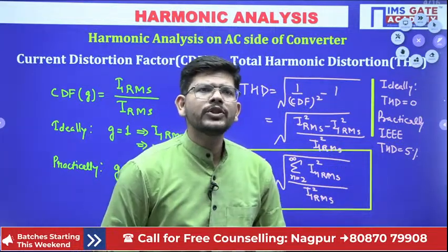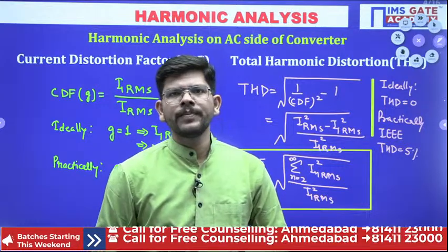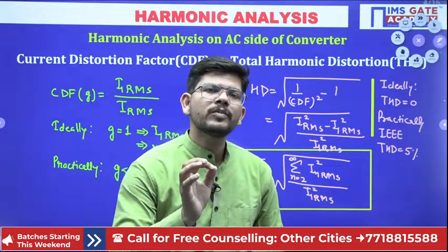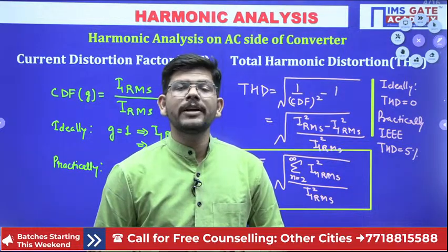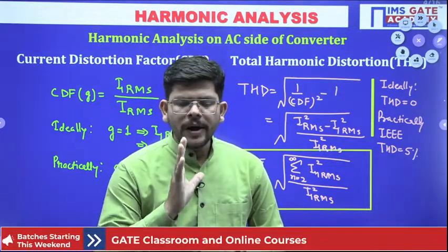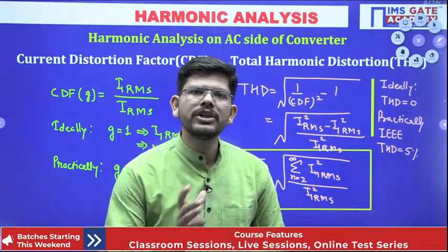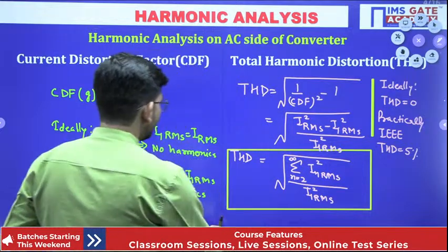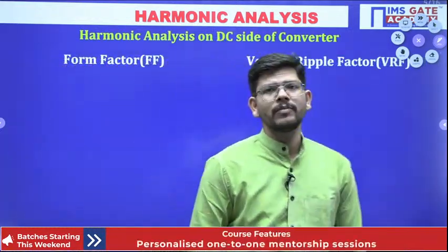So if I ask you, if we want to have the perfect sine wave, then what are the values of CDF and THD in case of a perfect sine wave? The CDF value might be equal to 1, only the fundamental component will be there, and the THD value might be equal to 0 only.